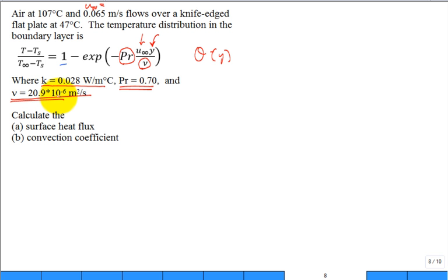All right, so we'll pick it back up here. So how do I calculate the surface heat flux? Isn't that q double prime at the surface? And I think you had it. What did you use, in words? The Newton's law of cooling equation, that was the part for h, the convection coefficient. But if I just wanted the surface heat flux, what's coming? So minus k sub f partial T with respect to y at y equal to 0.